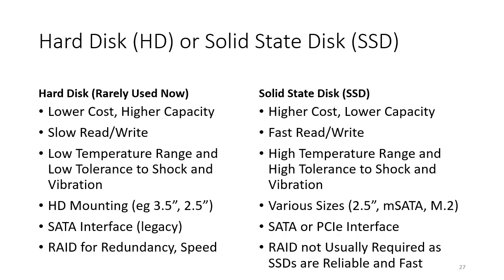The head isn't actually touching the plate. There's a very small distance between the head and the plate, and what can happen is if there is shock or vibration to the hard disk, the head can actually hit the disk, and then that can damage the electromagnetic substrate, and that can cause damage to the hard disk itself. And if there's severe shock and vibration, that wears out the bearings as well.